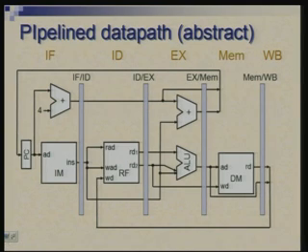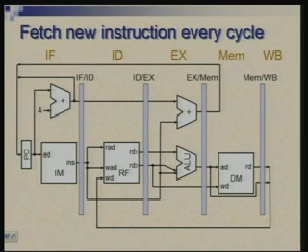So, we need to quickly be ready with PC plus 4 in the next cycle itself, and therefore, I carry out a slight modification of the data path, in that the multiplexer, of course, I am not showing the multiplexer here, but the multiplexer which selects between PC plus 4 and PC plus 4 plus offset is actually placed within the first stage.